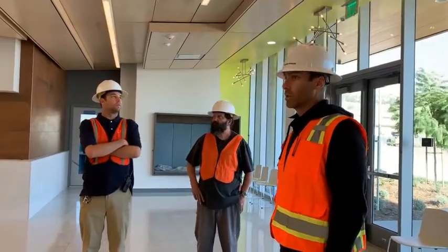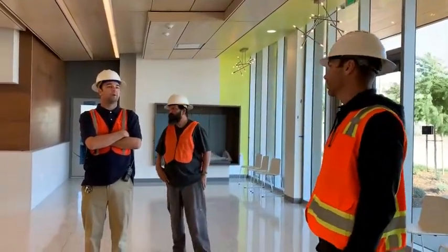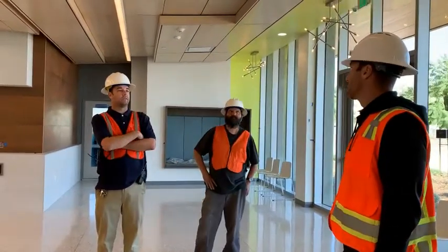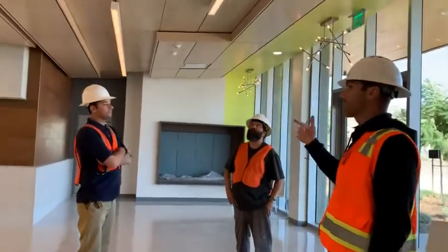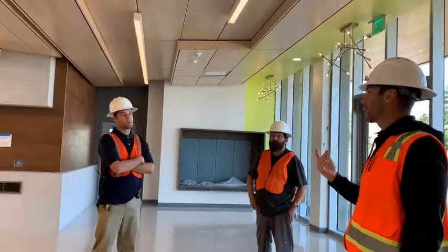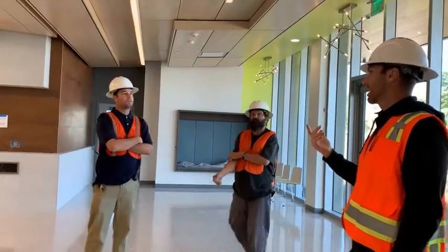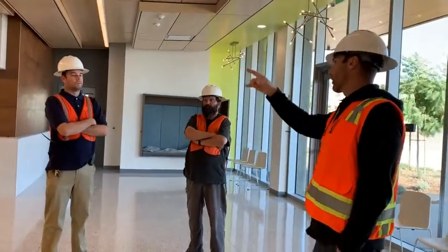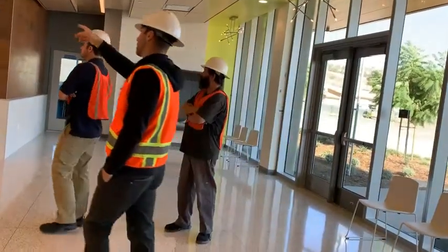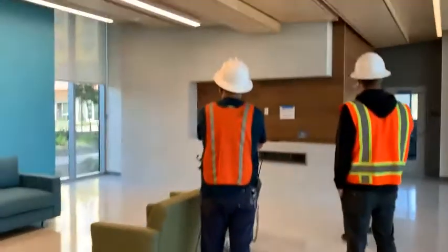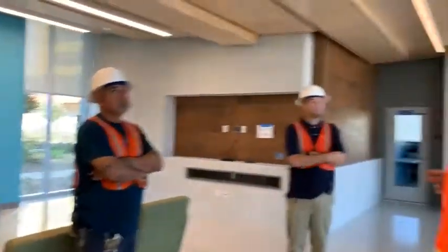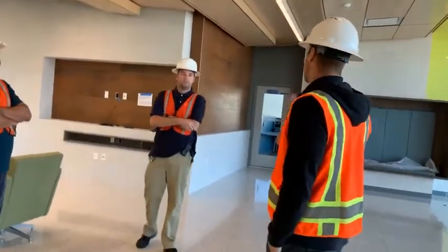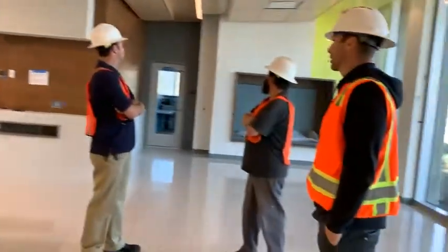Okay. And the daylight harvesting, is that just programmed? There's no sensor for that or anything like that? Well, the sensor's reading the daylight. The sensors all look the same, but what we use is a combination sensor sometimes, or sometimes we'll use just an individual daylight sensor. So if you look over there, see how the lens on this one is flat? Yeah, that's a daylight sensor. The ones that are rounded, even though they could just be an aux sensor, they could be both. Once it has an occupancy sensor and a daylight sensor, it still looks exactly the same. All right.